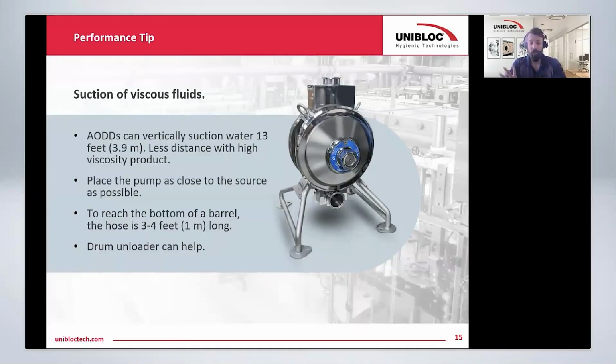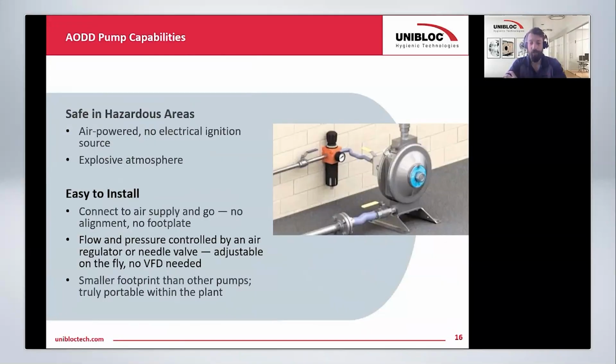So talking about pump carts and the mobility and the ease of install of these pumps, that brings us to another application where we had a packaging producer that needed to pump solvents, so some flammable materials at one of their plants. So they needed an ATEX pump. They needed it to be easy to maintain because this was a critical application. And so they selected an AODD because having it being air powered means it's kind of intrinsically safe. There's no risk of electrical ignition. They're easy to maintain.